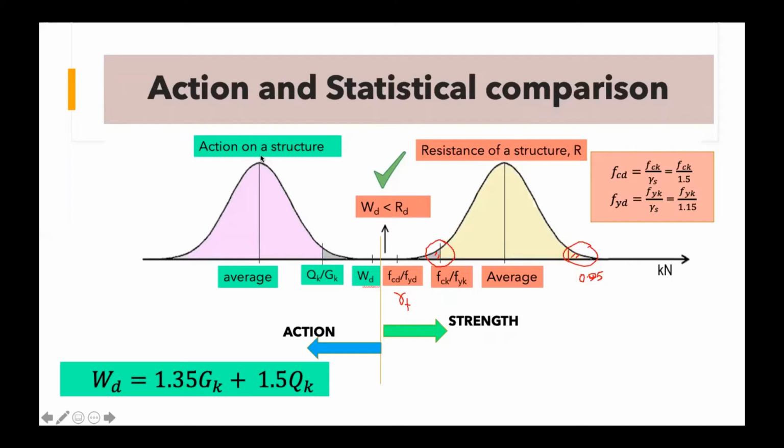But for the load, for the action on the structures, a similar procedure happens. For example, the weight of concrete: we test many samples, like 100 samples, since 100 is easier for us to calculate the percentage. We test them and get the load sustained by the concrete. This is permanent action. If we consider the permanent load, we get GK at the 5% upper tail. For the strength, it is the lowest here, but it is still greater than the GK here. So we get GK here.